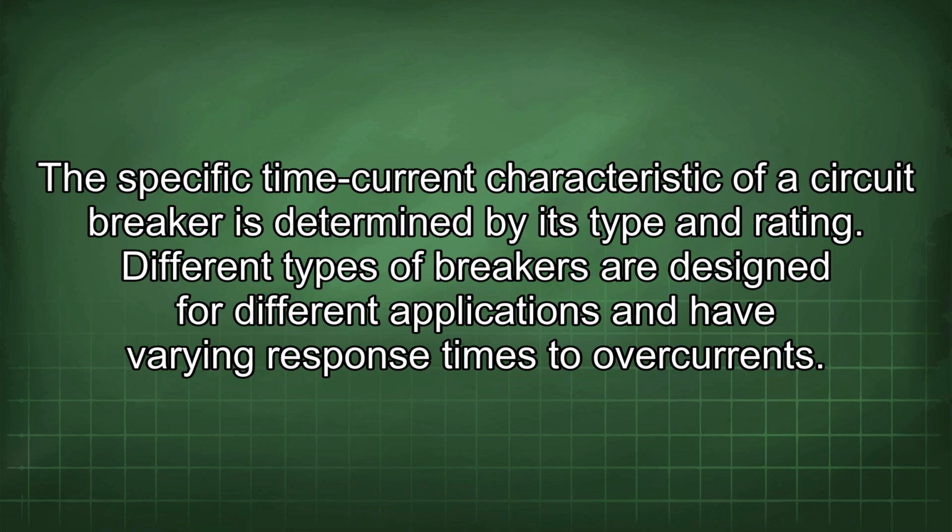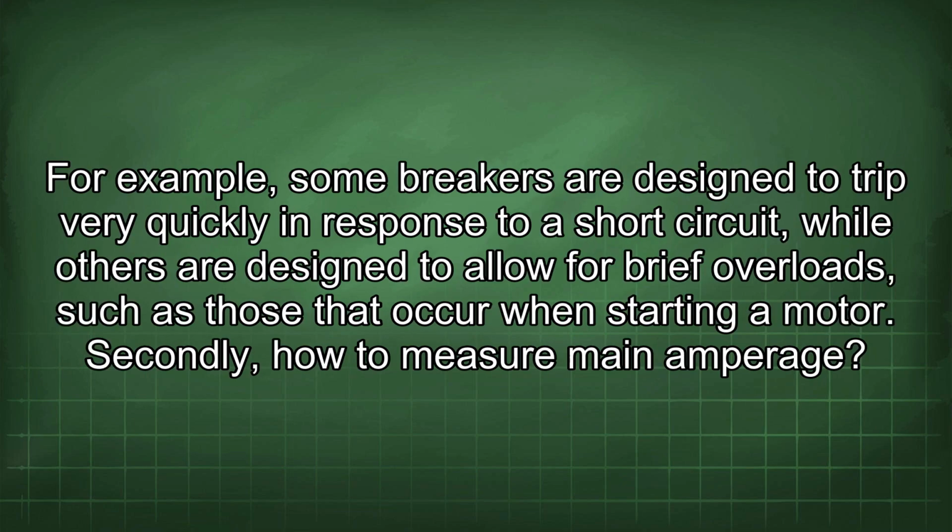Different types of breakers are designed for different applications and have varying response times to overcurrents. For example, some breakers are designed to trip very quickly in response to a short circuit, while others are designed to allow for brief overloads, such as those that occur when starting a motor.